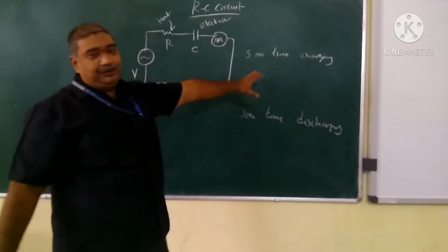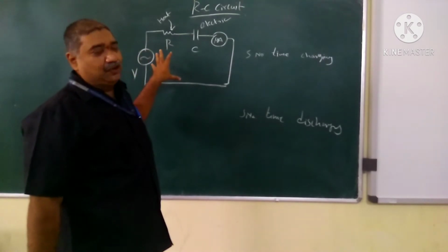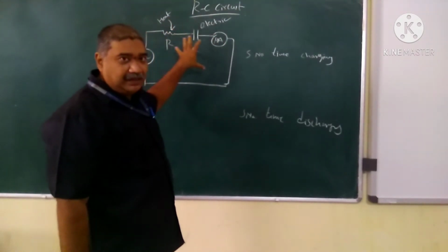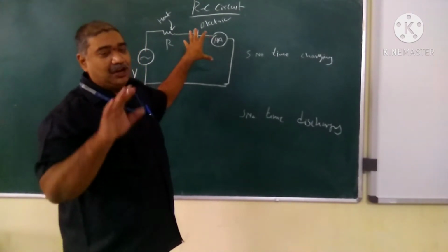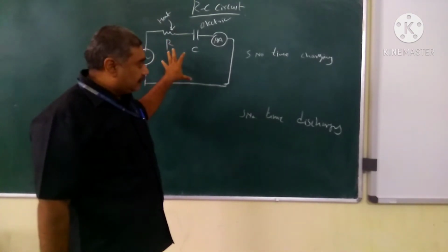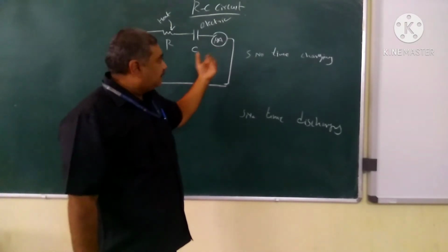So here, what is it that we are going to do? We are going to connect the circuit. After connecting the circuit, we are going to take the stop clock and measure, with respect to time, how much time this whole combination takes to store the maximum energy. In short, or in a reverse way, with the same circuit, we are going to take a stop clock and see how much time it takes to discharge the energy.